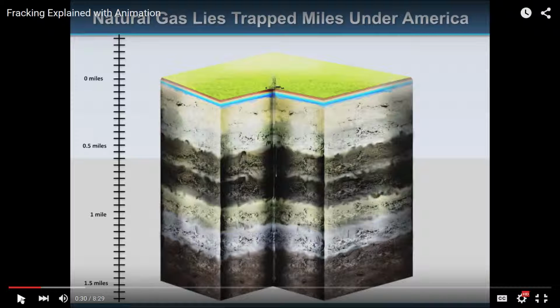But the oil degrades at certain temperatures, but these fracked-out reservoirs are still deep enough and produce enough heat that we can use binary plant generation, where you use organic compounds that boil at lower temperatures to run your turbines. Likewise, you don't have to run that saline solution or that dirty steam through your turbines. You have a cleaner system. You re-inject the fluids then, and this is the same technique we use for oil and gas.